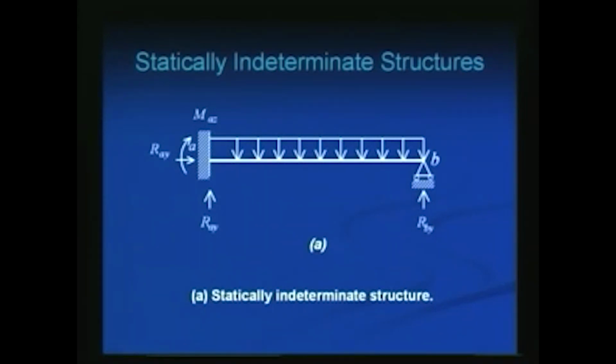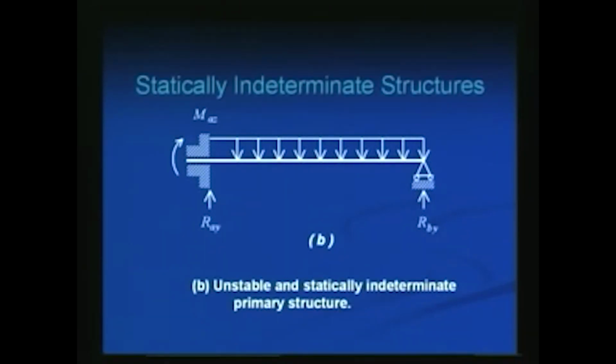Why? Because if you look at it, how many support reactions? 4. And how many equations of equilibrium? 3. So it's a statically indeterminate structure. Now let me have a look at another one.